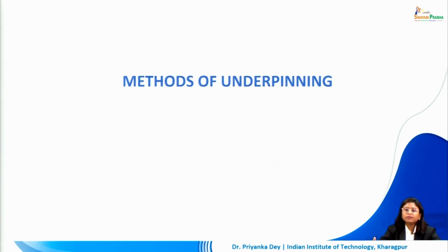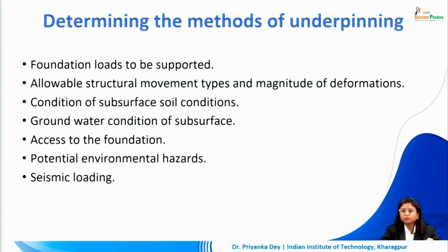So now that we are well aware of what underpinning does and what is the situation in which we can use underpinning and how we can prepare for it, let us start learning about the various methods of underpinning. Before we determine what is the suitable method of underpinning applicable to our construction, we have to see what are the foundation loads that have to be supported, what is the allowable structural movement, and what is the magnitude of deformations that I could possibly allow and what is expected to happen during this process.